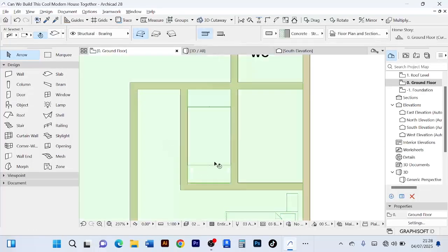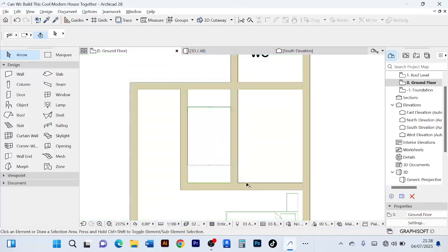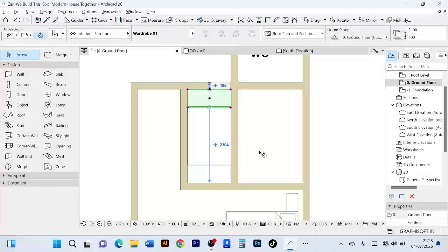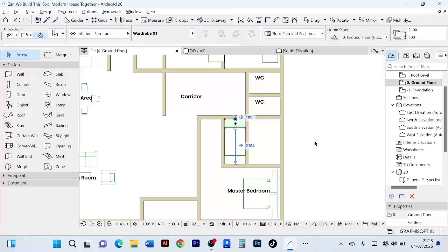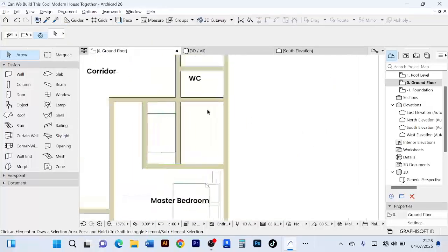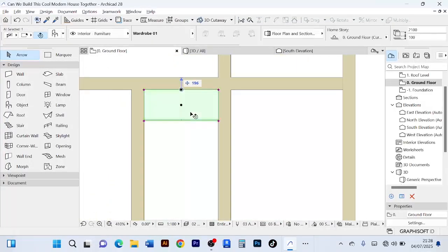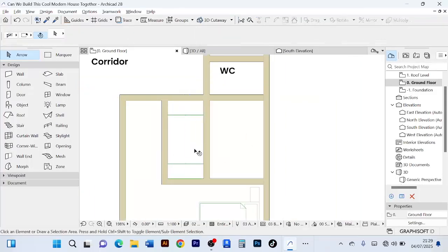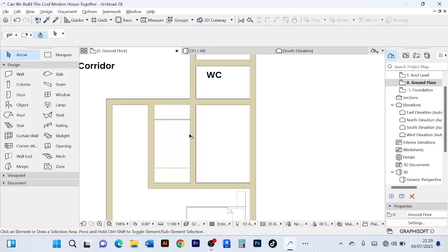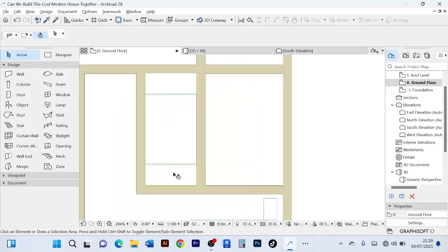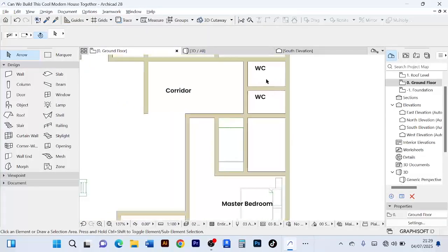You see, now we have this and that through mirroring a copy. But of course, I can also just drag a copy. You just press Control Shift D to drag a copy, and then you bring it here. However, for me, I think mirroring a copy is better because it even rotates the angle for you perfectly.